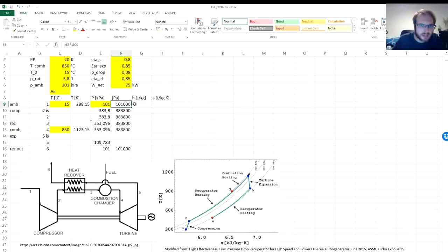And I noticed I have it mistaken here. No, it should be correct. So that is the pressure at point 5, and it needs to be the same also, of course, as the pressure 5 isentropic, because it's just an auxiliary helping value, where both of them, 5 isentropic and 5, would correspond to the same isobar, same pressure level.